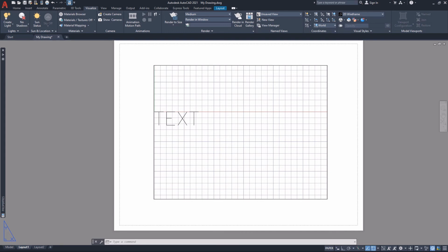Left-click one time on the border of this viewport window frame to select it. Note the change in the drawing aids toolbar at the bottom right of the display. With this viewport frame selected, a few extra icons show up in the drawing aids toolbar. One is a small padlock that, when selected or turned on, prevents any changes in the scale factor assigned to this viewport window.